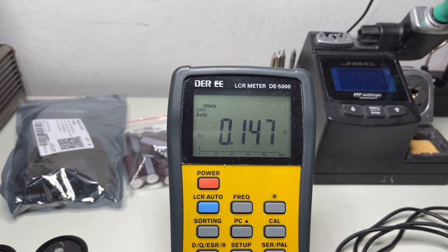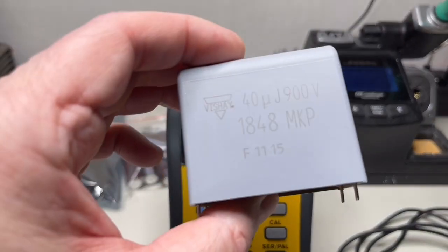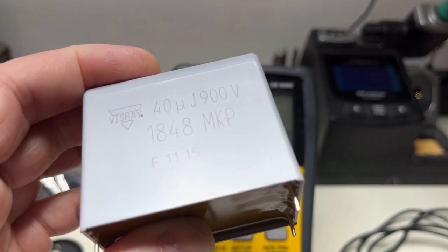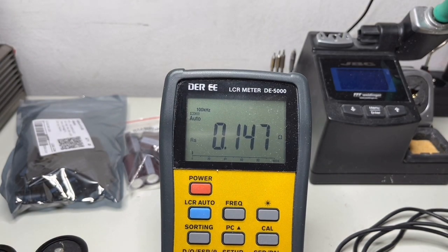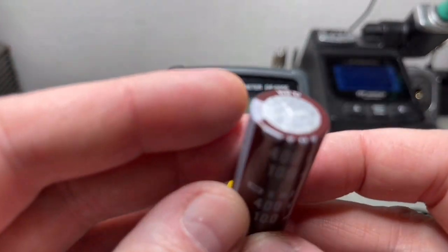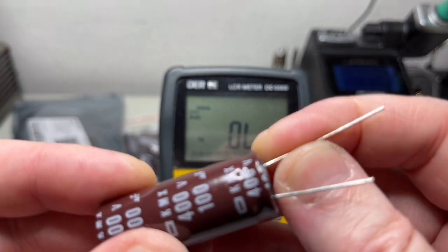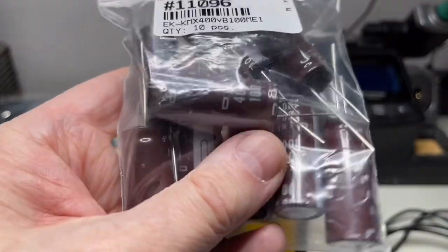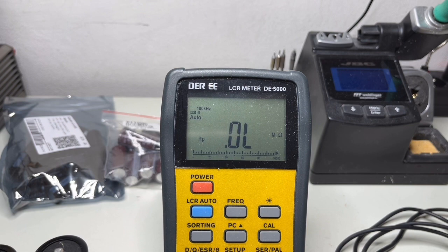It's 150 milliohms, yeah? Again, two of those in series is 0.3, so 300 milliohms compared to the 8 or 7 milliohms of this beautiful capacitor, sorry. Even these beautiful, high quality, original Nippon Chemicon capacitors. Many.